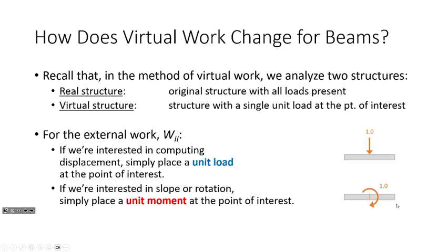How many of you have ever been in a house or a building that had a plastered roof? Like, how many old roofs have plaster on? So the idea is that if the beams start to deflect more than L over 360, you'll start to crack the plaster. That's kind of the idea. That doesn't mean that the beam's going to fall down and kill somebody, but obviously we don't want to crack the plaster. So that's, for example, where some of these deflection limits come from.